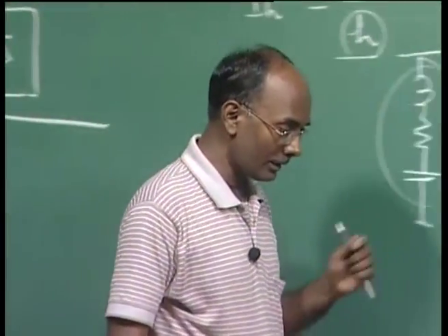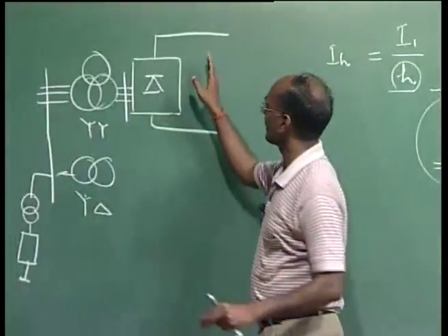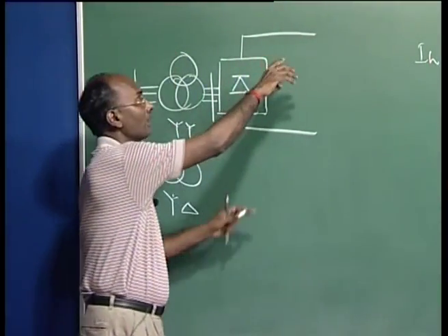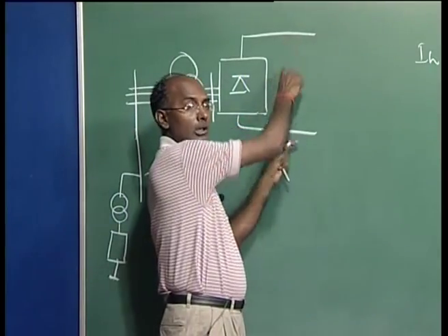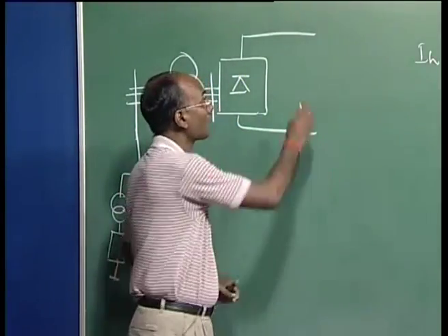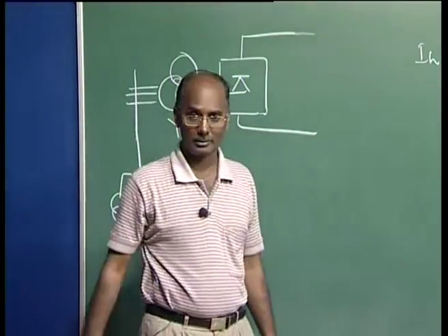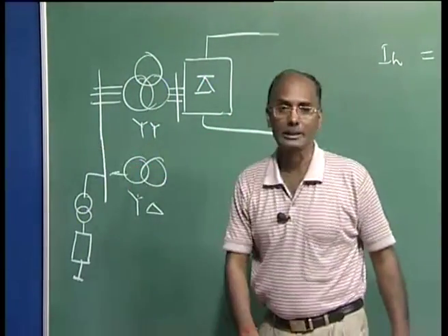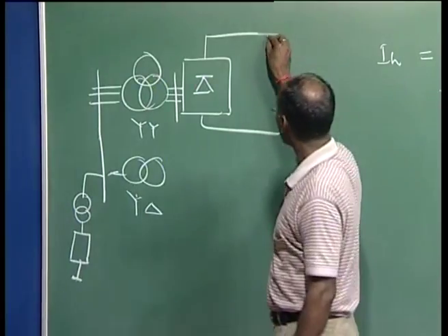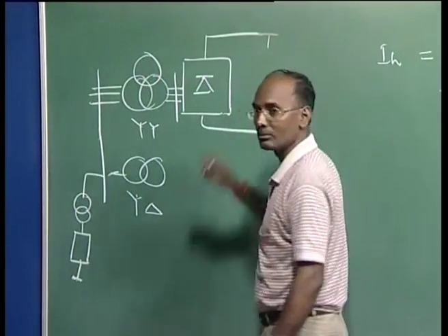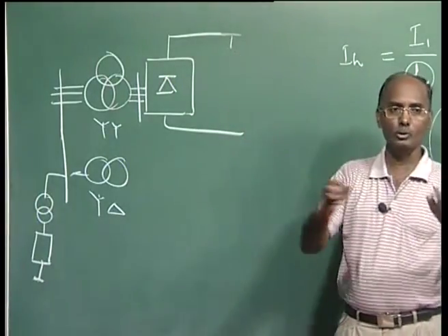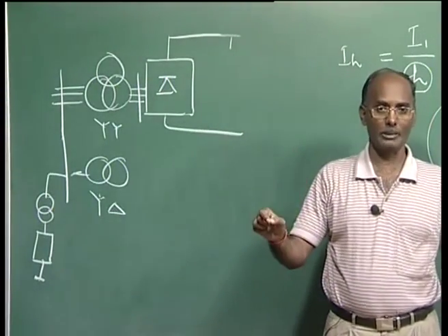Another is the DC side, because on this side we are getting the AC current harmonics, and here we are getting the DC voltage harmonics. So we put the filters as usual, and that filter is nothing but your smoothing reactors. We put the smoothing reactor this side, and that's why the DC reactors are put. Sometimes we also put some reactors in shunt for the voltage, because for the current we want the smoothing reactor to make the current constant, with ripple minimized.